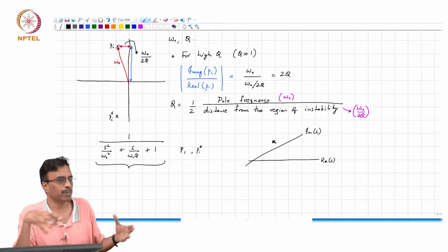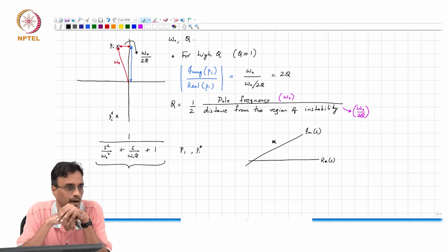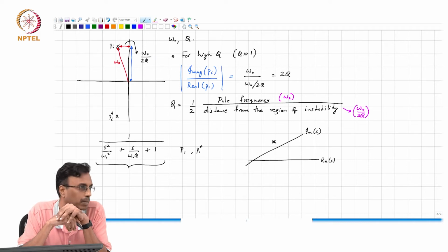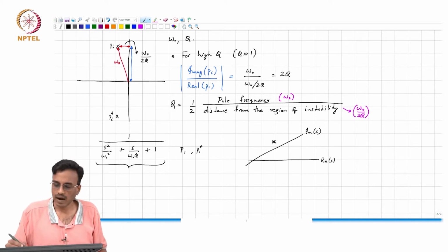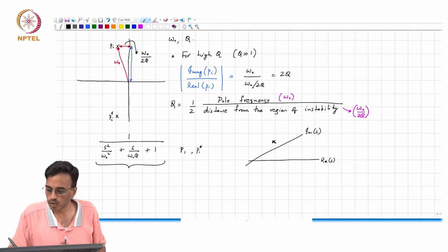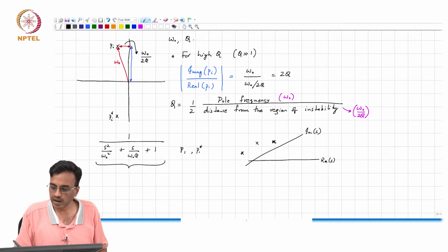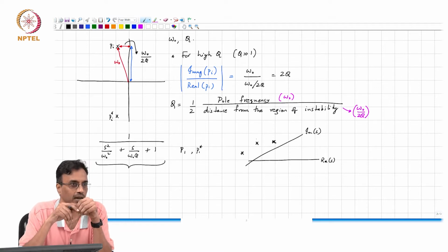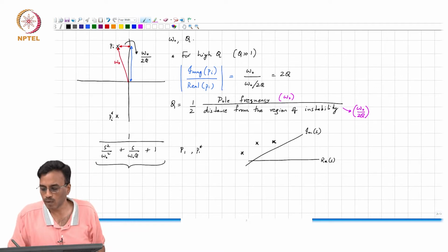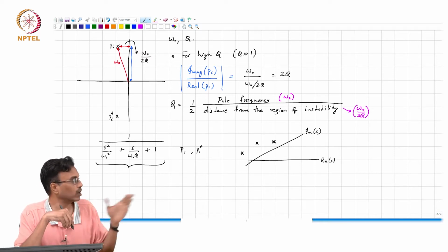Now, if I look at a 3D plot, how will the magnitude plot look like? It will tend to infinity at the pole, right? And if you have a filter transfer function with a whole bunch of poles, at each of these points what you will see is Mount Everest, right? But when you evaluate H of j omega, what exactly are we doing on this picture?